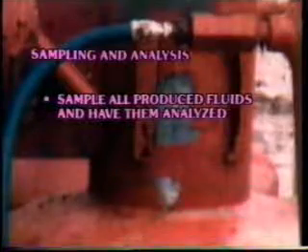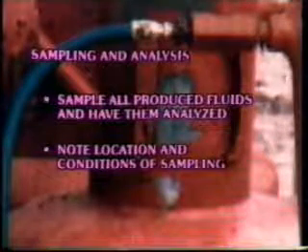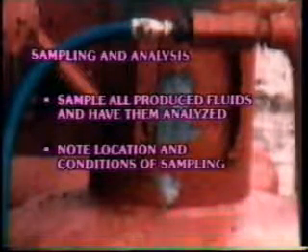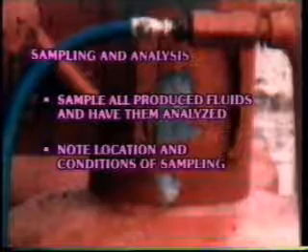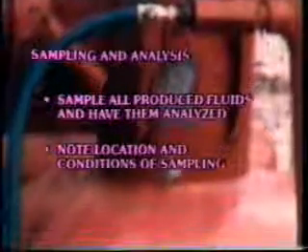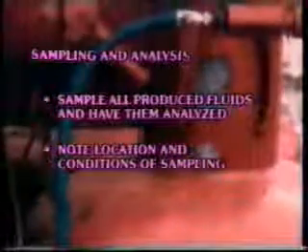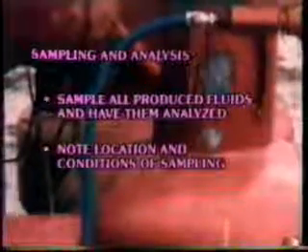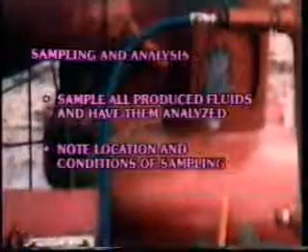Liquid samples should be taken at separator conditions so as to avoid the calculations required to convert stock tank volumes to equivalent separator conditions. Of course, reference should always be made to more accurate sample data that might have been collected soon after the well was discovered.